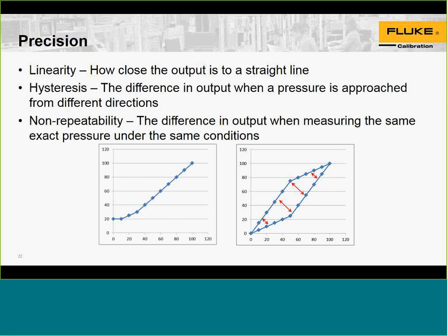That is the hysteresis of the sensor, and as I mentioned here, you may be able to minimize this by having a downrange, where if you only went to 50% of the sensor full scale, this could be half or even smaller. So hysteresis and linearity make up the conformance specification of a sensor.